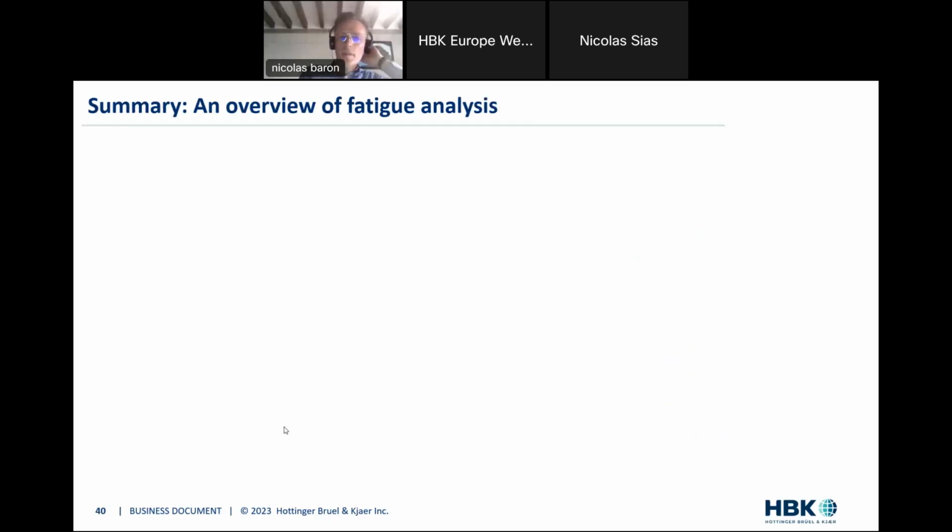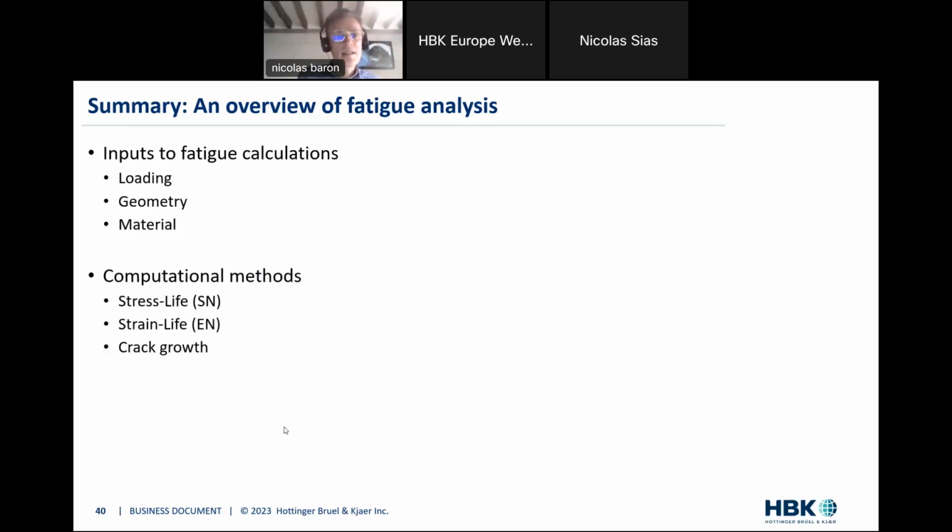So I hope I'm not going too fast. We are reaching now the overview of fatigue analysis. So what do we need for doing fatigue calculations? We have seen before, remember this 5-box chart that we covered some minutes ago, we had 3 different inputs for fatigue: geometry, loading, and the material aspect. You cannot do any fatigue calculation if you don't have all of these 3 characterized well enough. And again, I'm insisting on the loading part.